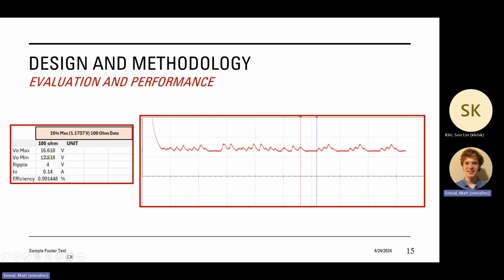It's still near our range of 600 millivolts. But when you go up to the upper end, it's quite bad. It's about 4 volts, so it doesn't look very good. So that definitely needs to be taken care of with varying either frequency and or duty cycle, depending on the load and depending on the input voltage.